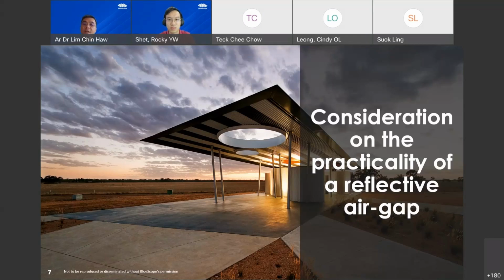Having said that, the long-term performance of the aluminum foil is also subject to the installation location. I'll give you an example. Let's say you install this reflective insulation in a very dusty environment, for instance a factory that produces wood furniture. You have a lot of dust.